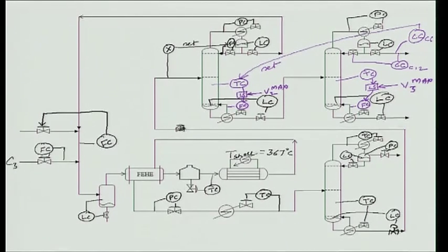I cannot afford to lose benzene product impurity control. So, therefore, this temperature controller on the recycle column has to be always on. What that means is I cannot have V2 max ever going active, because if it goes active, then I am in trouble. I am losing benzene impurity control.